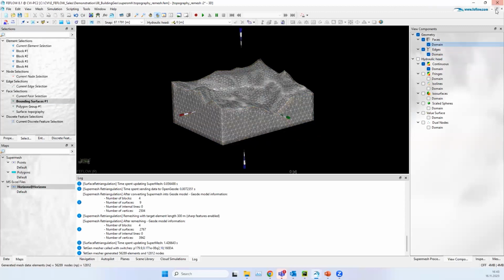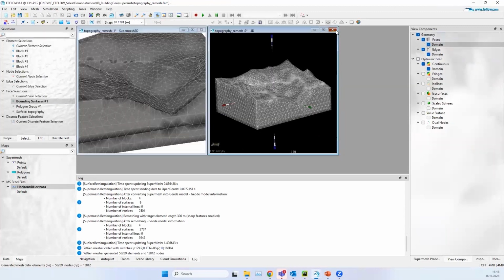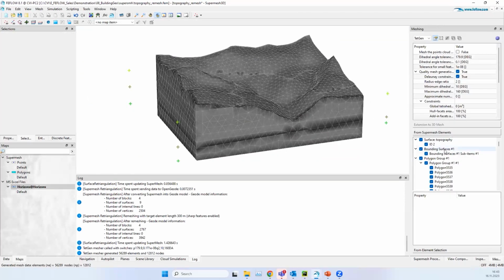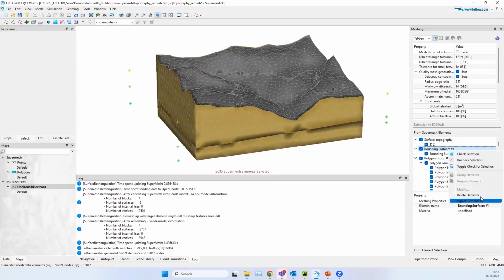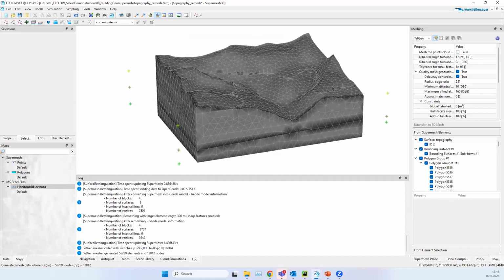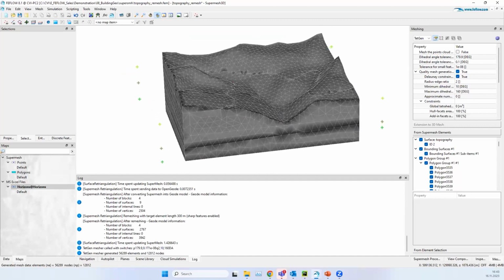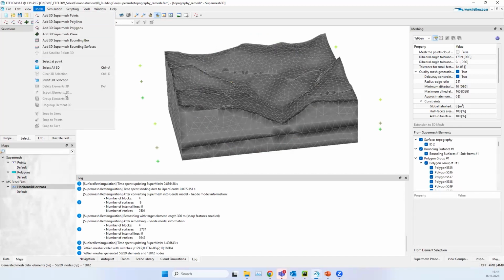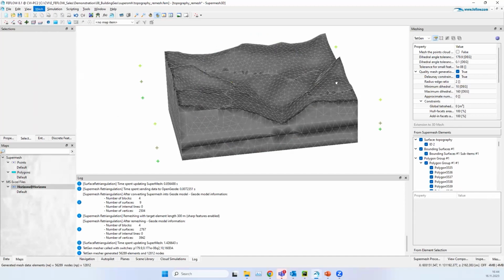Okay, so in case you forgot or you want to do something, you can go back. In the new FEFLOW, you have the possibility to select information. And if you don't need anything, you can just simply delete this. If you are happy with the distributions of the surfaces and how they are, and if you don't want to repeat again and again, you can simply export this data. This is the possibility to export any surface, export elements, and then you just import in another project.